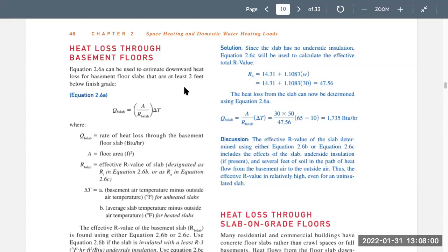If we're wanting to build a smart home, if we're wanting to consider a house that has good insulation or doesn't have a lot of conductive heat losses, then that's very important to consider as we move forward. The easiest way to look at these formulas is to really look at the examples. So I'll explain the formula, we'll look at the example, and we'll move on, and we only have a couple more of these. The nice thing is, in our thermal load calculator, we already have this as part of it. So you guys are already using it, but we hadn't really covered why.